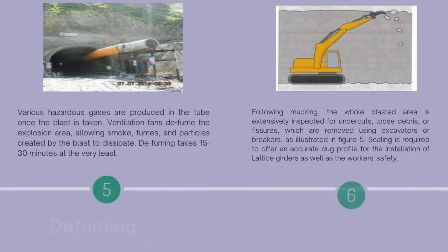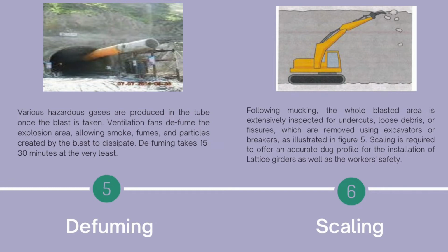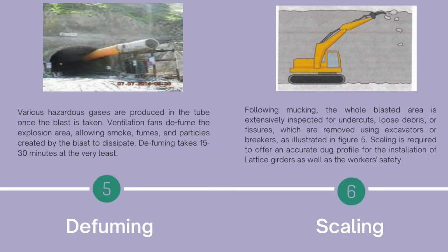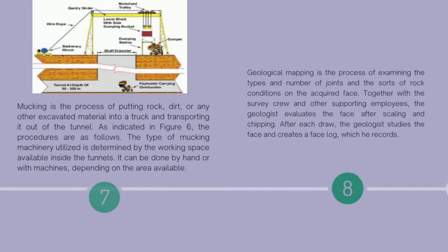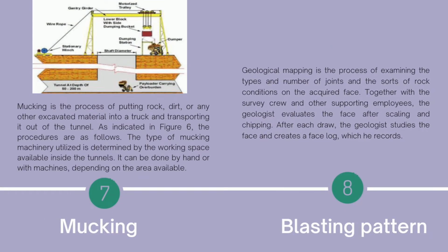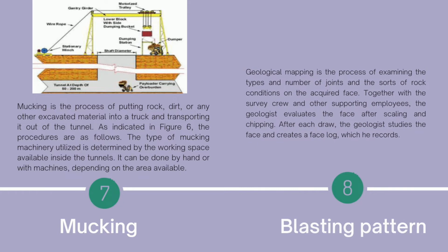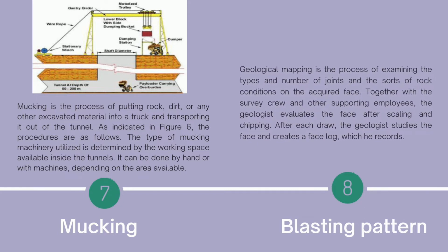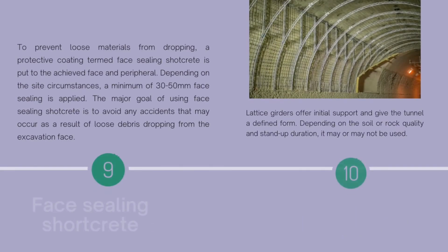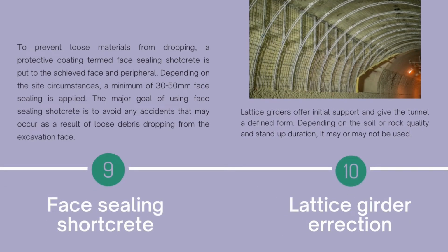Defuming. Ventilation fans defume the explosion area. Scaling is required to offer an accurate profile for the installation of lattice girders. Mucking is the process of putting rock, dirt, or any other excavated material into a truck. Geological face mapping is the process of examining the types and number of joints. Face sealing with shotcrete is to avoid any accident that may occur. Lattice girder erection offers initial support and gives the tunnel a defined form.